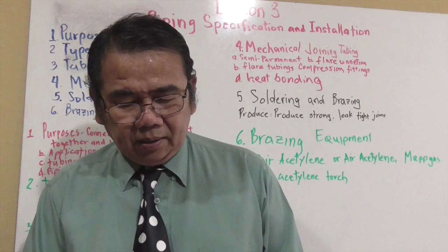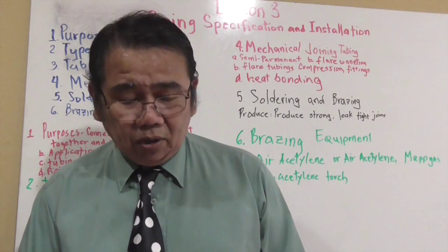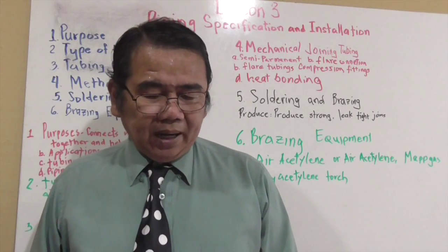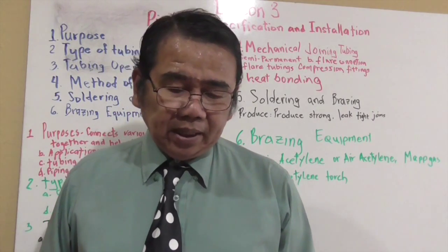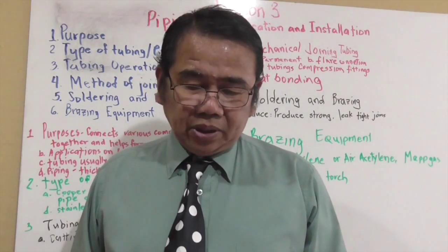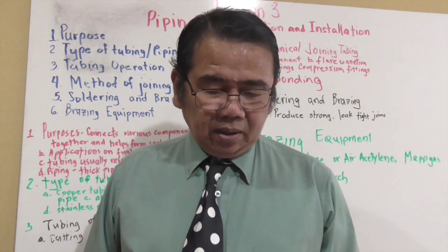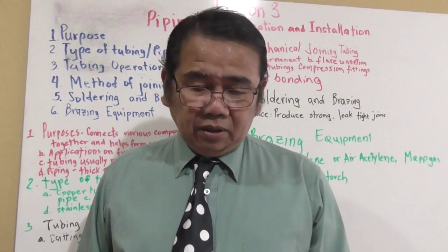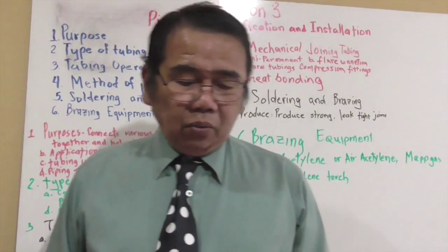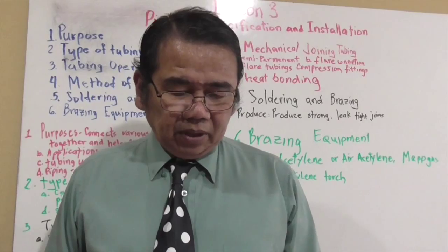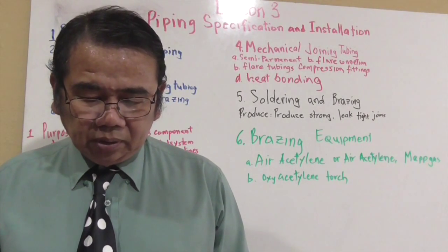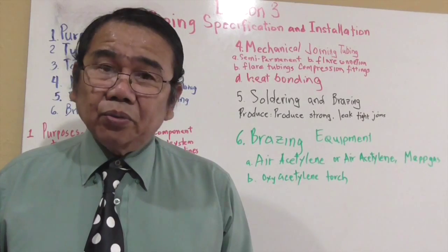And then for heat bonding, we've got the soft solder. That is 95-5, containing 95% tin and 5% antimony. It starts to melt at 430 degrees Fahrenheit and is fully liquid at 535 degrees Fahrenheit. Recommended soft solder to use on refrigeration work.